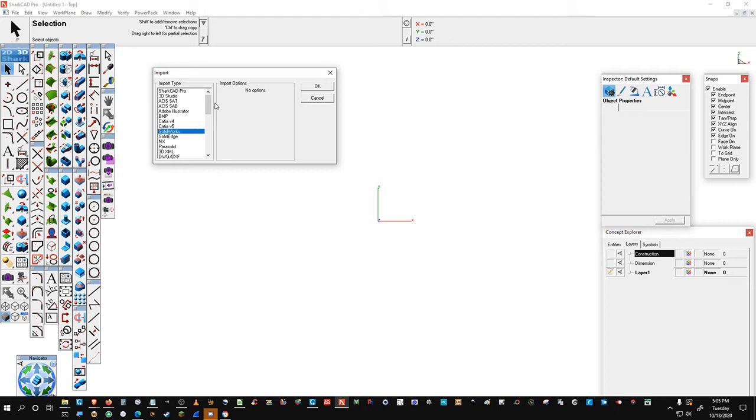Now it will import SolidWorks, but up to a certain year. It won't import the newer SolidWorks files because SolidWorks, they're the type of company, they want everybody locked out of their software. That way they can corner their market. Solid Edge, probably up to the latest version, they're the same as SolidWorks. But if you do STEPs, don't worry. STEPs can go from program to program. IGES files can go from program to program. NX, Parasolid, 3D XML,